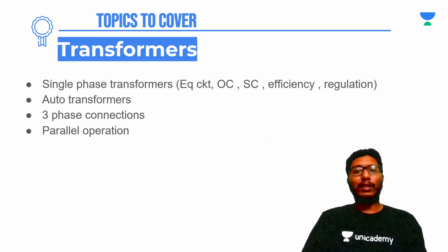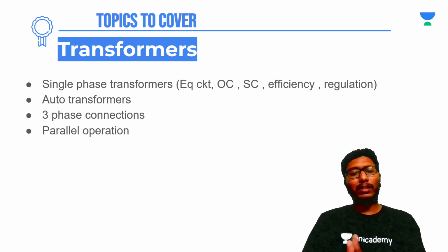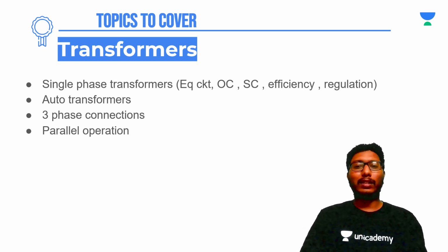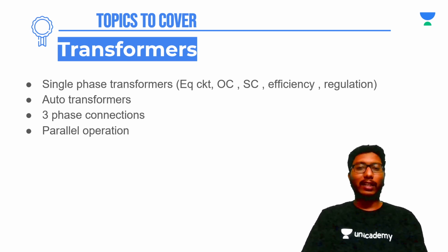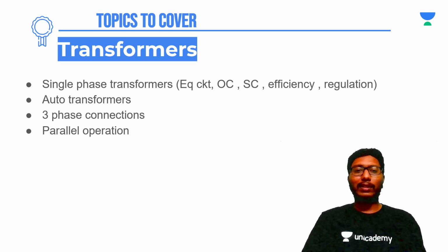One more thing you should take into consideration is that one of the two transformers will have less loading. That means it will be fully loaded before going into parallel operation. So you should stop that transformer at that load, calculate the same for the other transformer as well, and add these two loads vectorially to get the total load supplied by these two transformers. Whichever transformer has less internal impedance will have more capacity and will share more load. This is another type of problem.